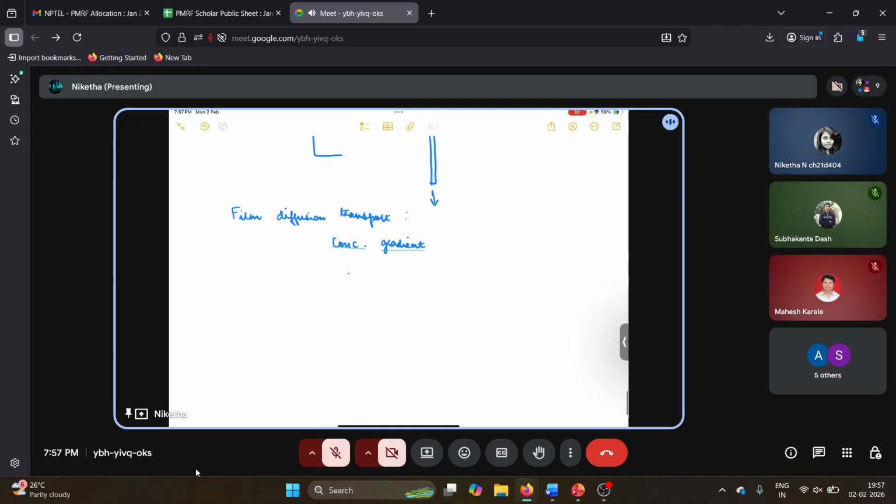So what this means is when we put the adsorbent inside the solution having some contaminant, for example, this is activated carbon. So this is a solid particle inside the liquid, right? Once inside, it will form a film. Inside the liquid film, there will be some kind of a partition. Here, this portion is called the bulk liquid, where the concentration of the pollutant is uniform.